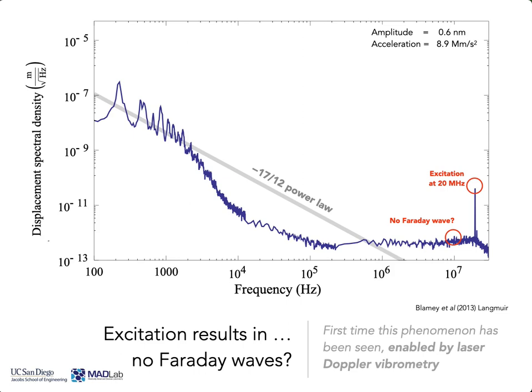Fascinatingly enough, we've shown over the years that with these large accelerations it is safe to use large molecules, even cells, within these fluids, and they survive the process. The reason is that the excitation tends to be away from around 10 kilohertz to 100 kilohertz, which seems to be the range in which a lot of large biomolecules, and for that matter, cell membranes and organelles, exhibit resonant behaviors that can cause failure or denaturation of these molecules and cell membranes.